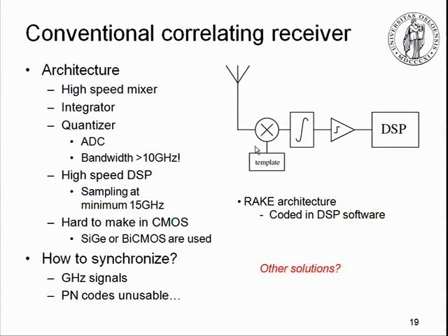Now that's a messy thing, because then I need to synchronize very accurately with my sender. Remember I said that we're shaping our symbols as pseudo-noise, appearing as noise. Now, how do you synchronize on noise? That's fundamentally very difficult. On one hand, we want to synchronize. On the other hand, we don't want to transmit frequency components, and that kills us. It makes it really difficult to synchronize. So I'll propose a solution to that.